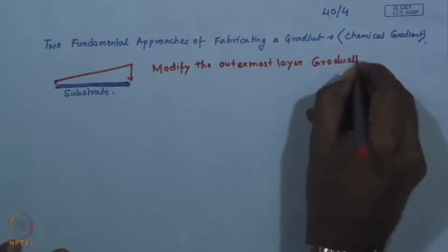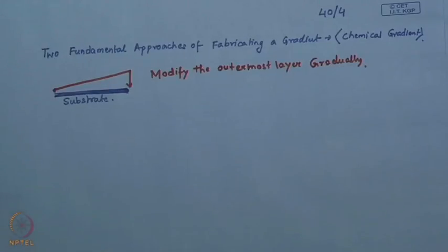So, let us say you have a surface layer or SAM coated layer, and you understand that by UV exposure you can tailor its surface energy. So, you have a SAM, self assembled monolayer coated layer, let us say, which is giving you a contact angle of 110 degrees.